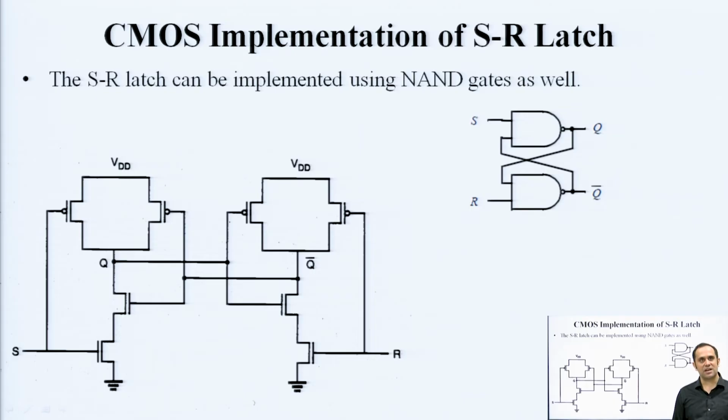Active high basically means that they will be true when the signal supplying them, or the wire supplying them, is at high voltage. So a NOR gate SR latch is an active high component, and a NAND gate SR latch is an active low component.